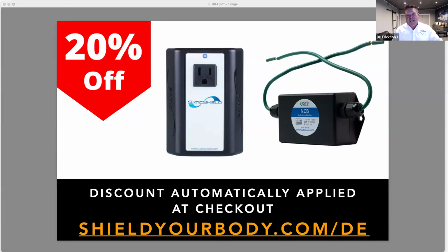And just the way a motorcycle goes up and down, as loads are turned on, the generator will come up to match that load. So you do want some filtering when the generator's on, but here's why a lot of times they're not compatible, because a capacitor becomes a phantom load. What's that mean? It means that it creates apparent power. What's apparent power?